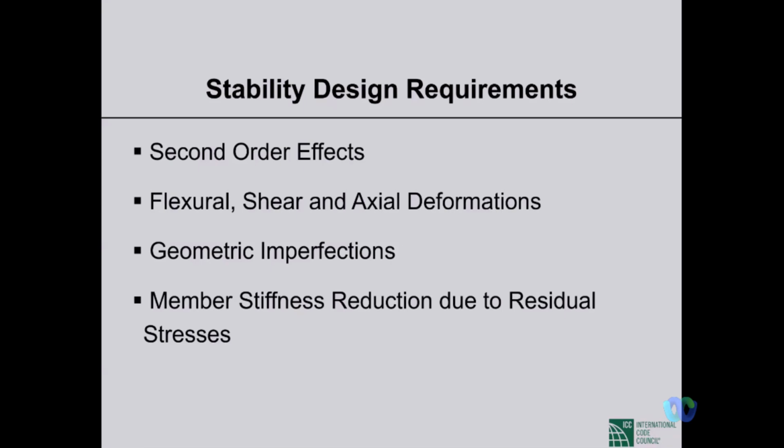We teach these things in third year, level 3, and fourth year. I'm sure that you have also read about this, studied about this in some way. But if we want to consider these geometric imperfections, we have to go for nonlinear analysis. And they also hasten the buckling. So geometric imperfections are important.